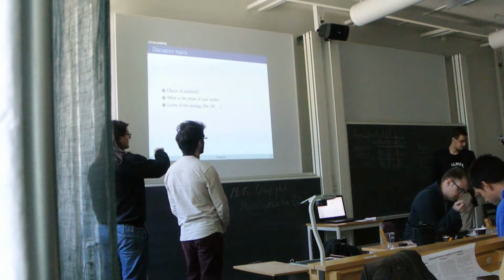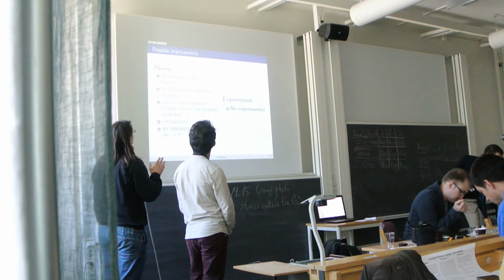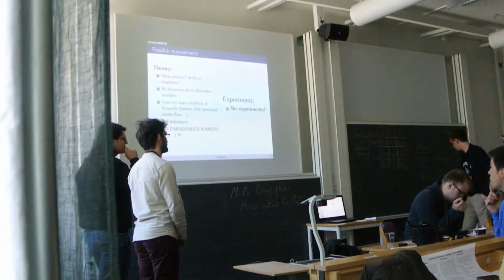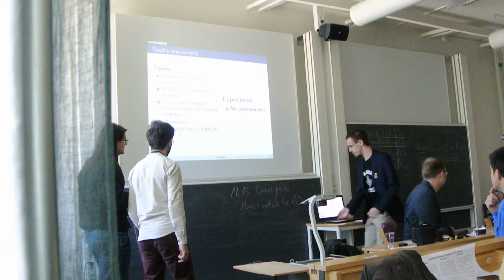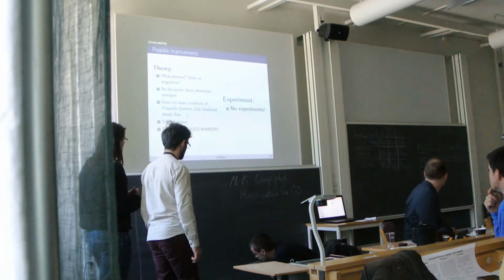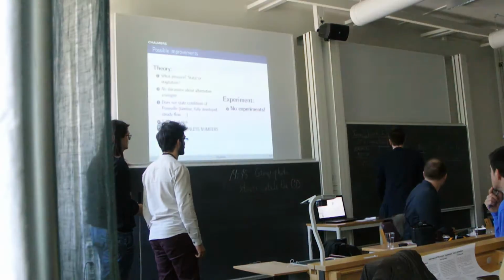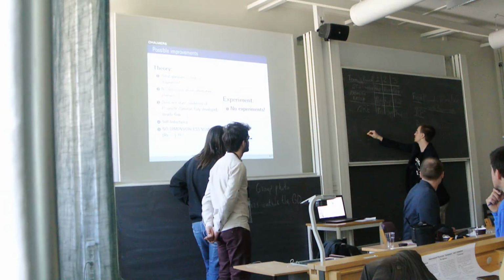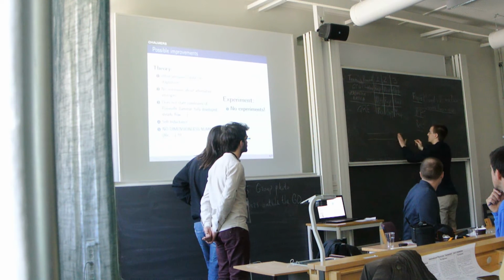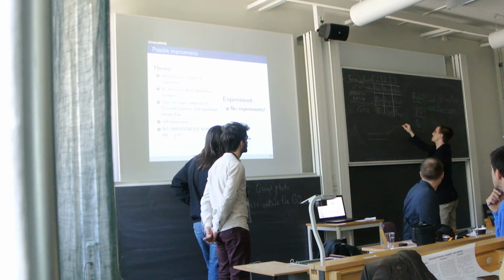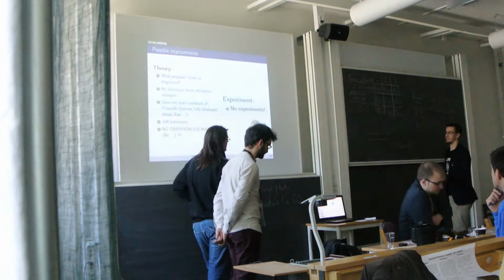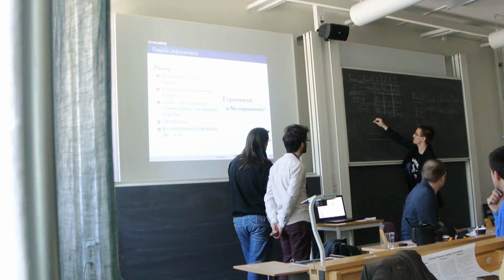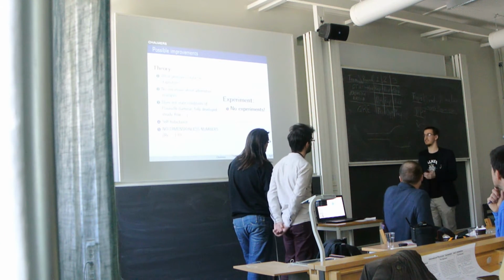Can you rebuild the previous slide? When you say static and stagnation pressure, what exactly do you mean? Okay, so let me show an image. Let's draw a pipe, and let's have it become wider. So the static pressure is simply if we would make a water column here and look at the height, then the height will be proportional to the static pressure.